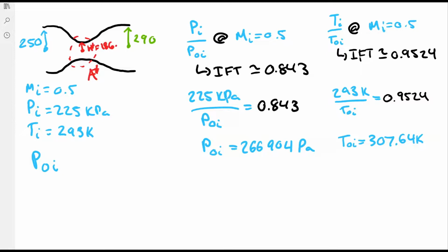we need to find the pressure ratio, P_E over P_0E, evaluated at the area ratio, A_E over A star, which, as we saw before, for a planar nozzle that has a width of 1, the area ratio is simply a ratio of the half heights of our nozzle.